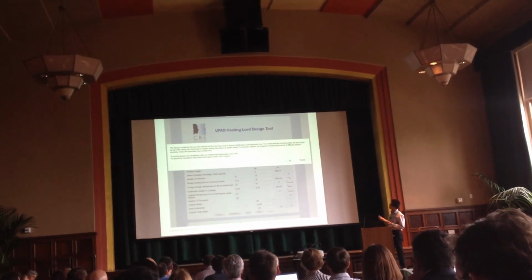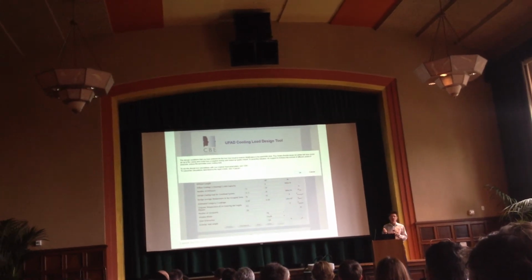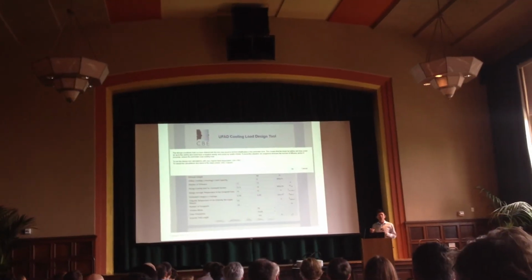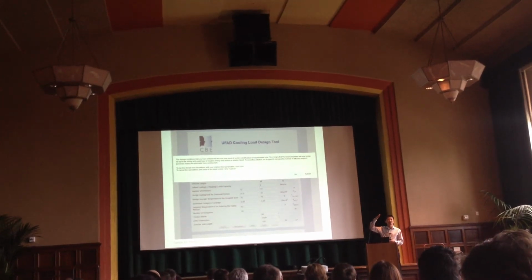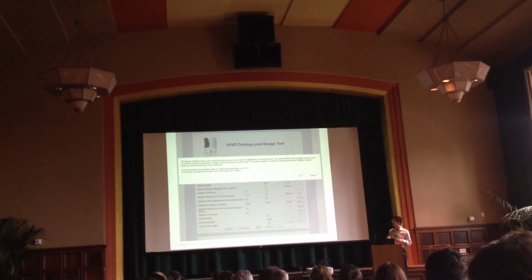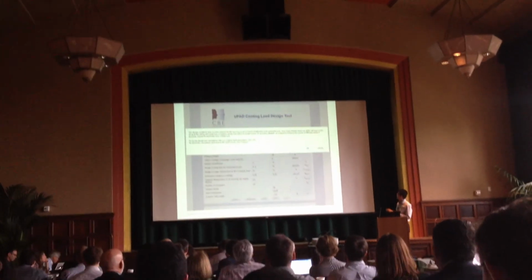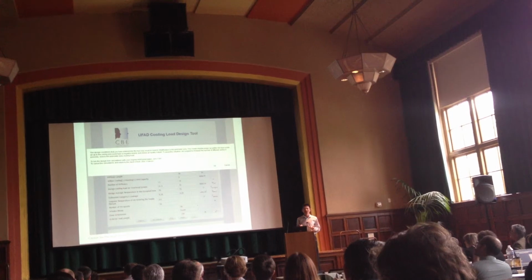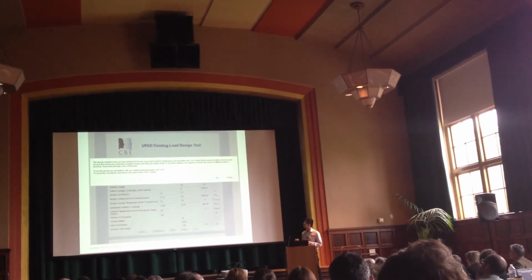And what would happen? It says the design conditions that you have entered into the tool may result in reverse stratification. What does it mean? It means the linear bar diffusers are throwing the cool air up to the ceiling, which makes the return air temperature maybe lower than the head and ankle temperature. So it says it has negative energy and indoor air quality impact, right? So how are we going to solve this situation? We can either increase the number of diffusers or we can reduce the cooling load in the perimeter zone.